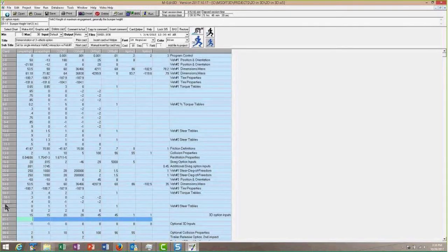So now here we just put in 15. I'm going to go ahead and grab the specs on these. They're not going to look right until we grab the specs, but I'm just going to put in what's on the card above it. And one other point I've made before: if it's not a rollover, and this isn't, it'll run faster if you put a 0 in for the node friction, fields 7 and 8.